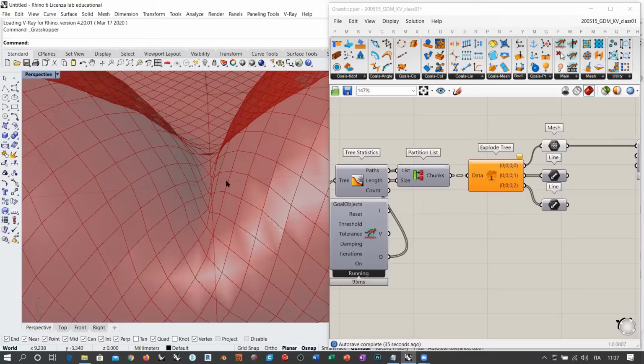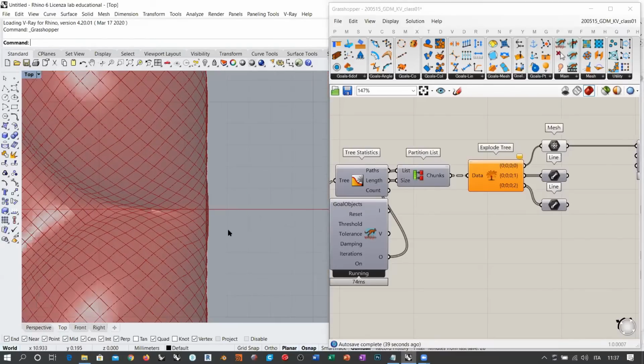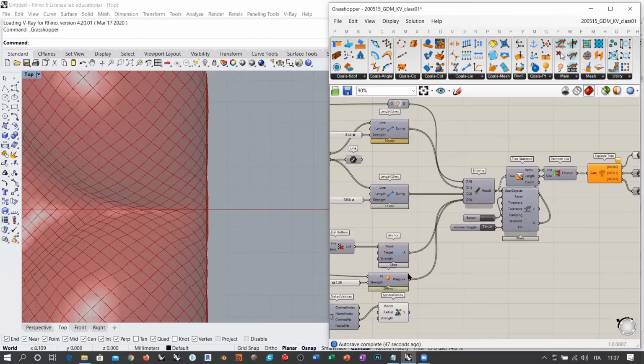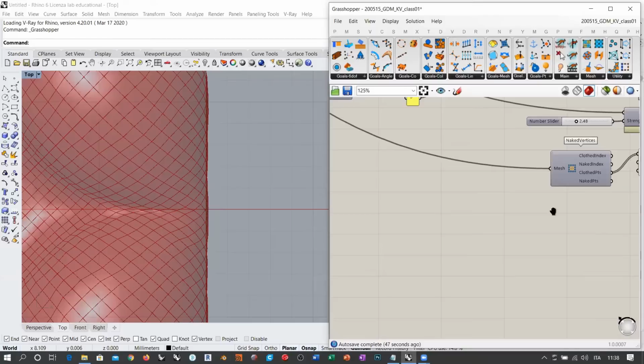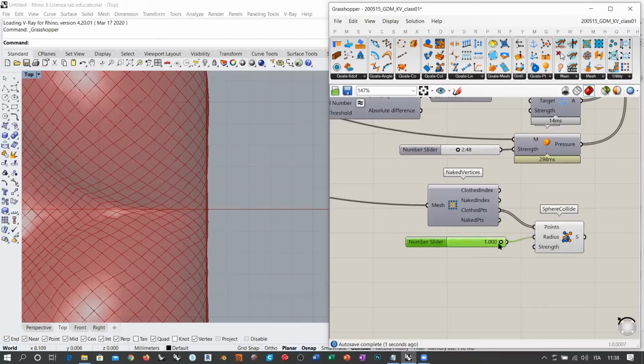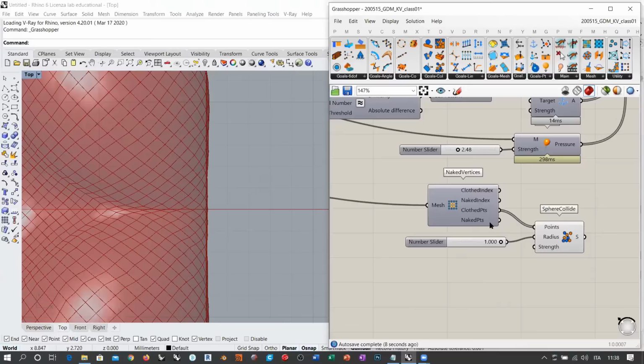And if we go into the top viewport, you see that compared to one square of our grid, we are considering something like decimal values, okay? So the radius for my spherical light must be something very, very small. So I will take 1.000 as the radius, which I know is going to be too much, because one radius means this distance between the vertices. So this is going to also expand the mesh too much.